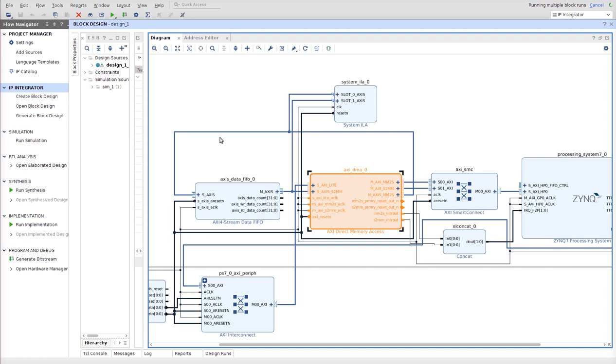And then once we add the DMA, we add a little FIFO just to have these two channels separate, and then you can see the transmission between them, and then you can trigger on valid signals. Because if it was a feedback here, it would not be easy to use some signals to trigger, because they might be on all the time. So yeah.